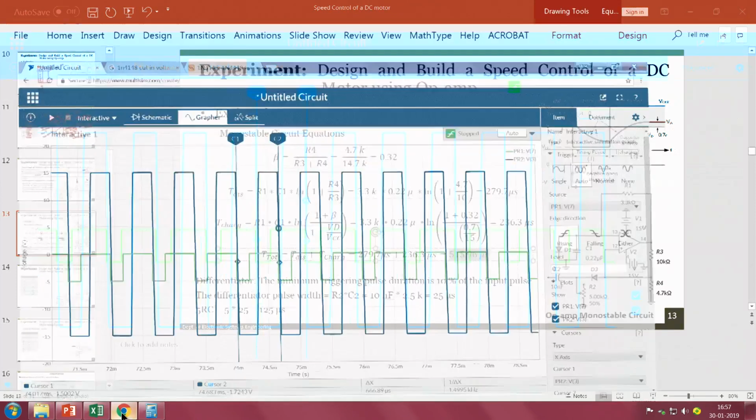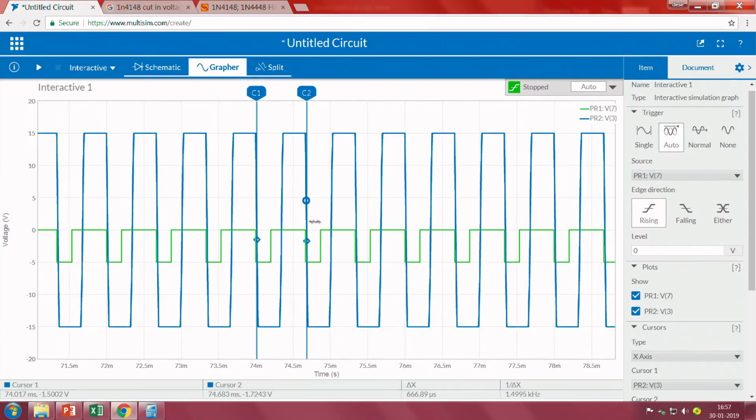But one thing is clear: no matter what, the complete signal time duration is not deviating, right. So wherever I have a negative spike, I am getting an on time, and we also have enough room for the capacitor to charge to 0.7. So there are no chances of missing the signal.